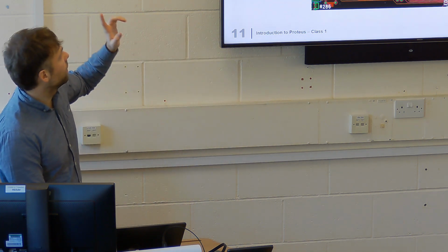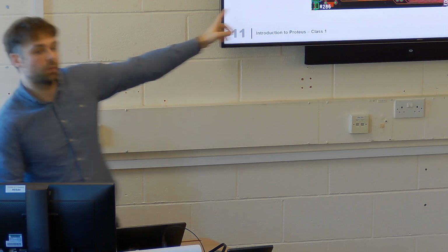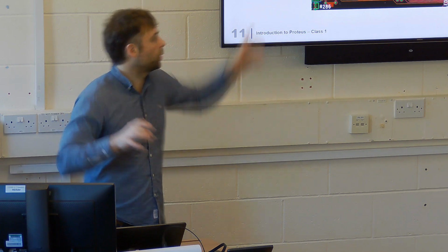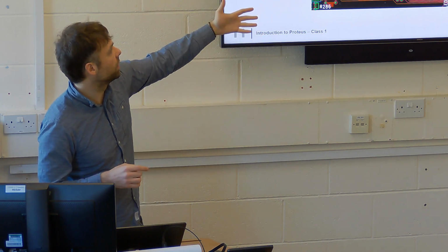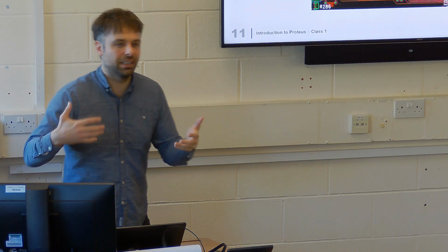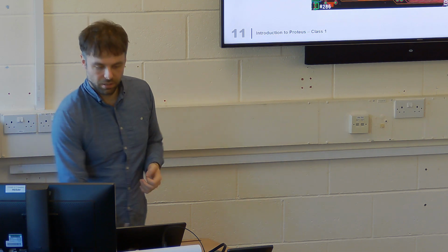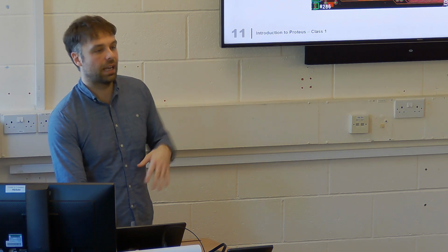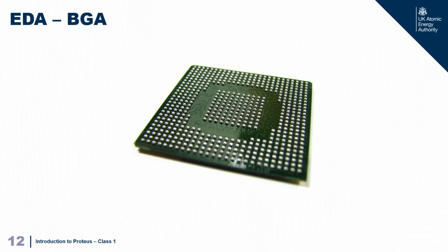So, one other thing, there's probably reference planes on here as well. Reference planes are solid planes of metal that are either ground or power, but I don't think they're visible on this drawing, because otherwise you'd just have blank. They're transparent on these designs, but obviously to see the traces, you just hide the reference planes. BGA, that's what it looks like on the underside of it.